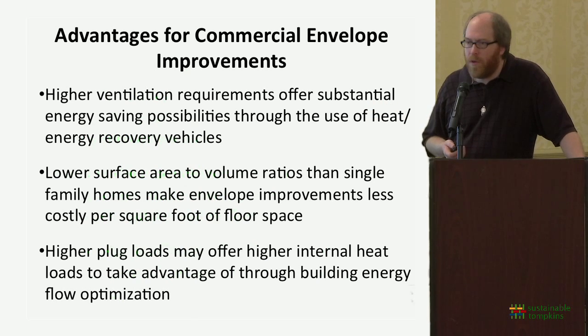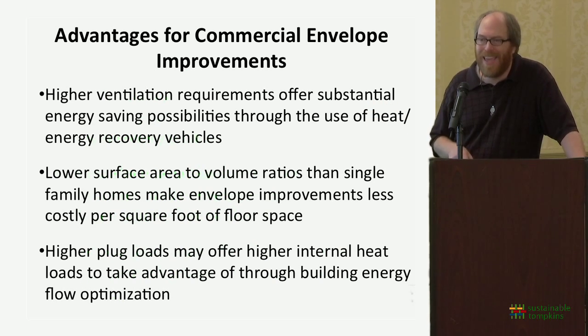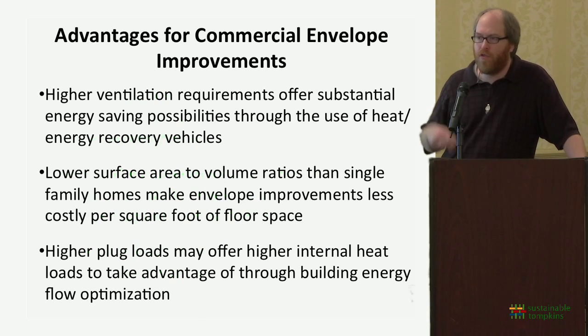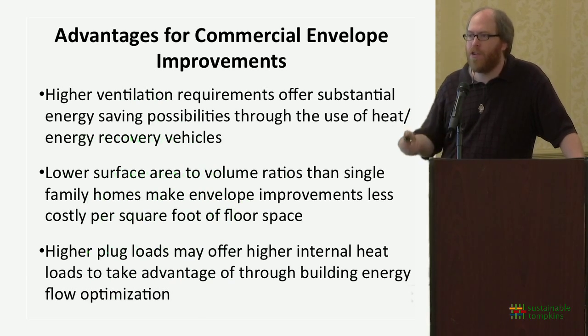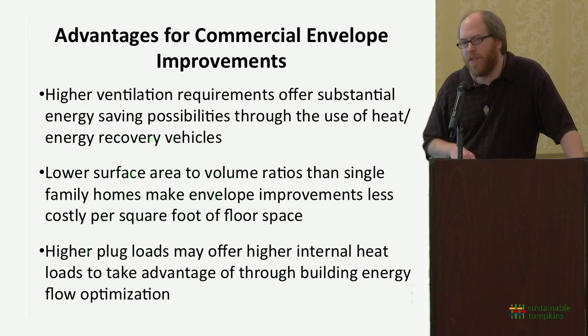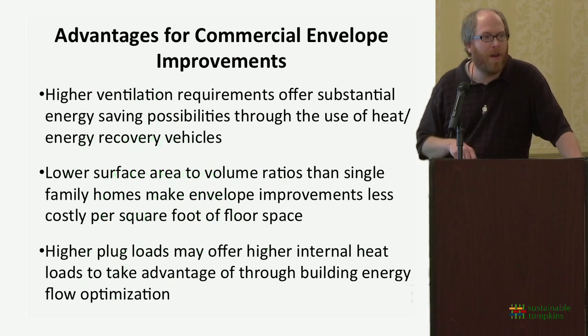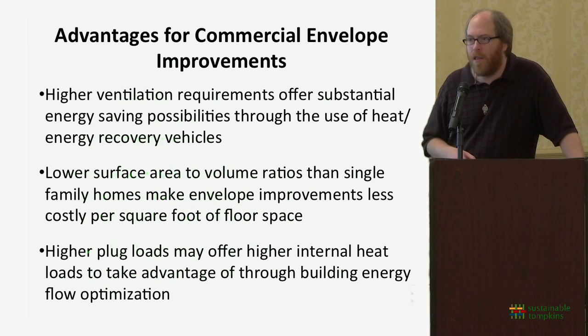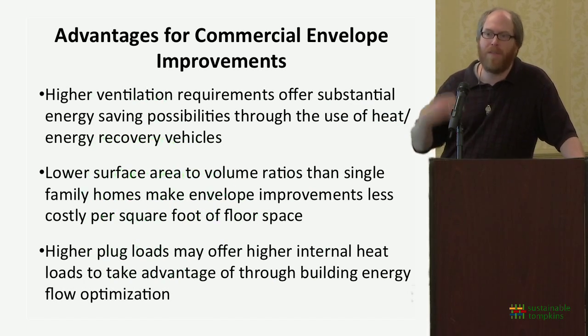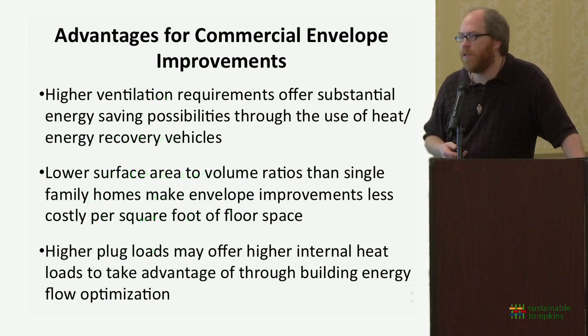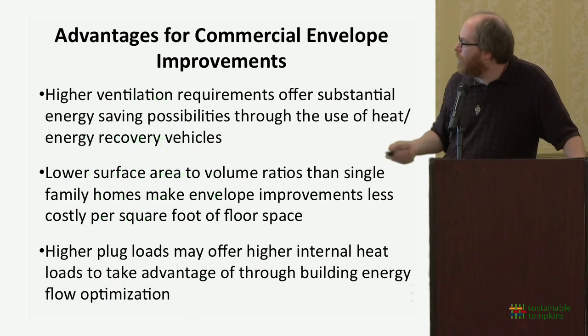One is that they do have much higher ventilation loads. Mechanical ventilation is going to drive the air changes for your building, and therefore the insertion of heat recovery or energy recovery systems that can recover part of that energy can generally be done at lower cost than in a home, where once you've tightened it up to a certain level, you have to add those mechanical ventilation systems that you wouldn't otherwise have had.